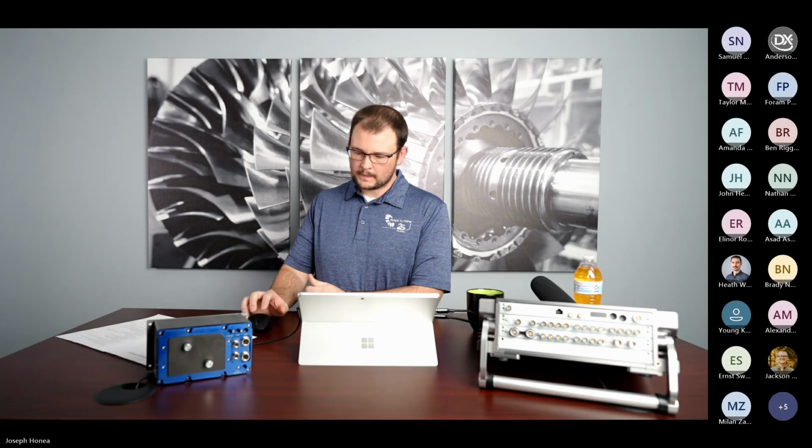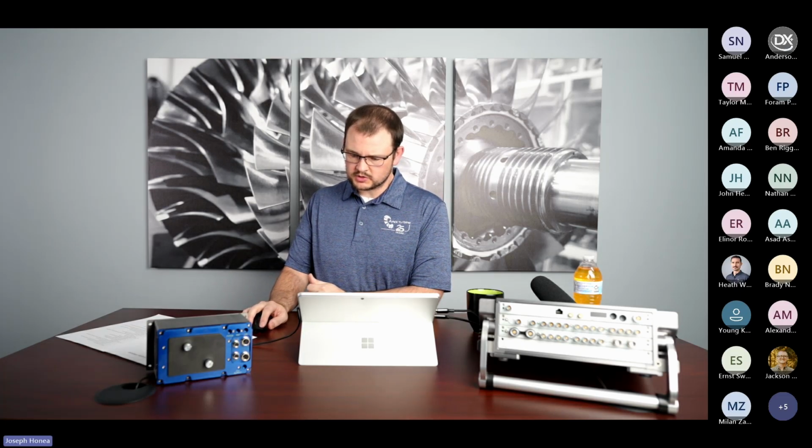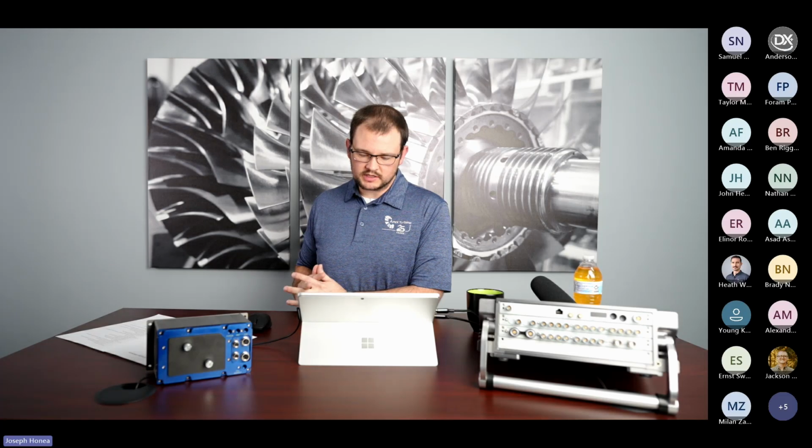All right, next question. What is the most efficient way to apply scaling coefficients, EUA, EUV, for sensor groups with multiple instruments that have different calibration functions? So the DX Plus provides an EU scaler, and this ultimately provides the ability to apply a polynomial scaling factor to the incoming data.